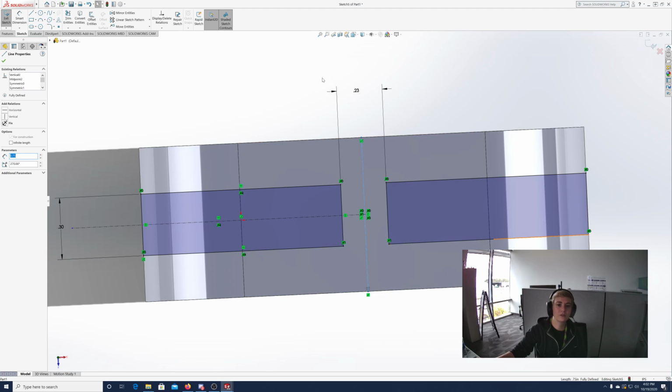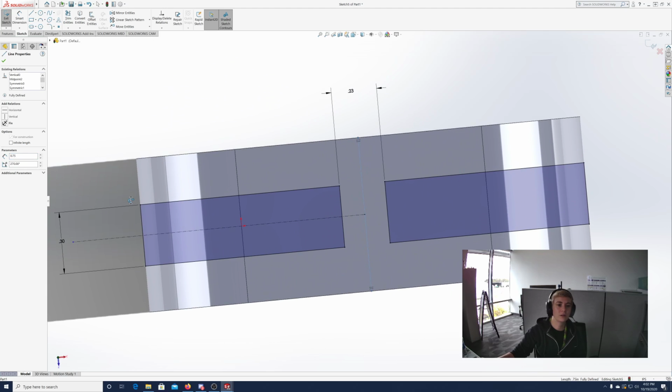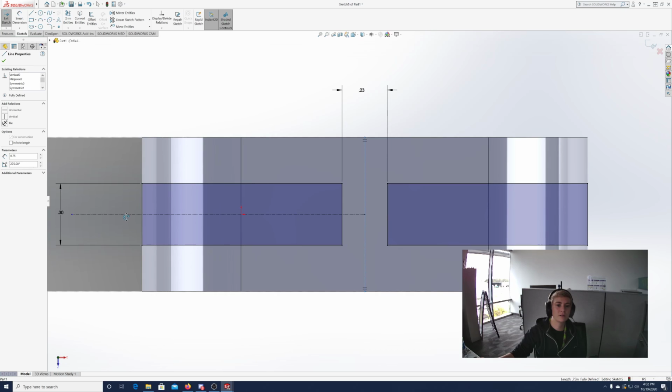Okay, you should have sketched it at the beginning of this sketch, so that might be the problem, that you didn't sketch that center line. That was the first step, this center line right in the middle of that top face. And then you did another center line going out to the side. The only purpose of the second center line was to put this rectangle that you're mirroring right in the middle of the part, top to bottom, if that makes sense. So that's the only thing you're using that one for. The one you're mirroring about is this vertical one that you did first.